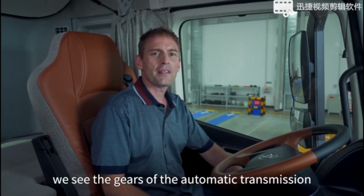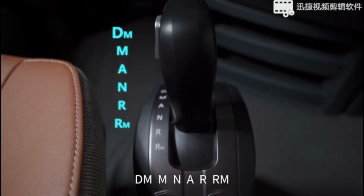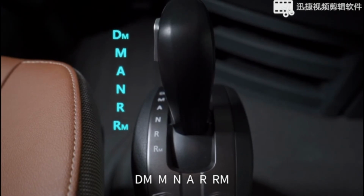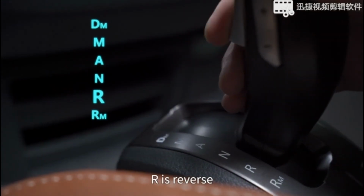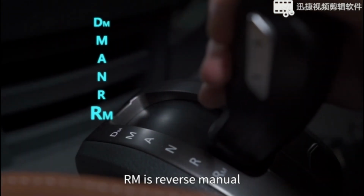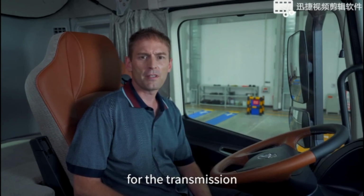Here in the cab, we see the gears of the automatic transmission. The ESTA-AMT has 6 gears: DM, M, N, A, R, RM. N is neutral. A is automatic drive mode. R is reverse. DM is drive manual. RM is reverse manual. Let's talk about the correct starting method for the transmission.